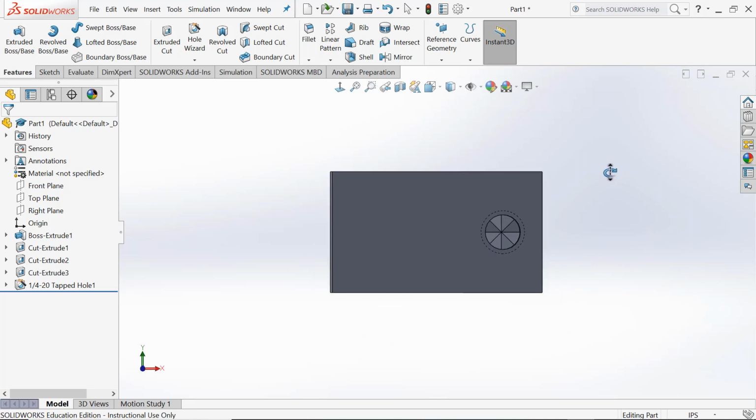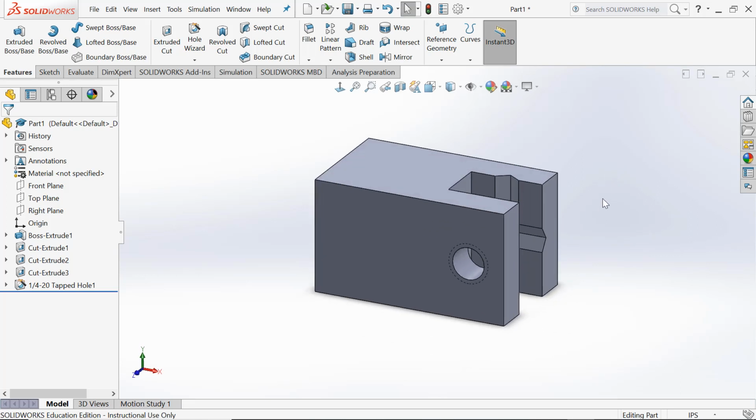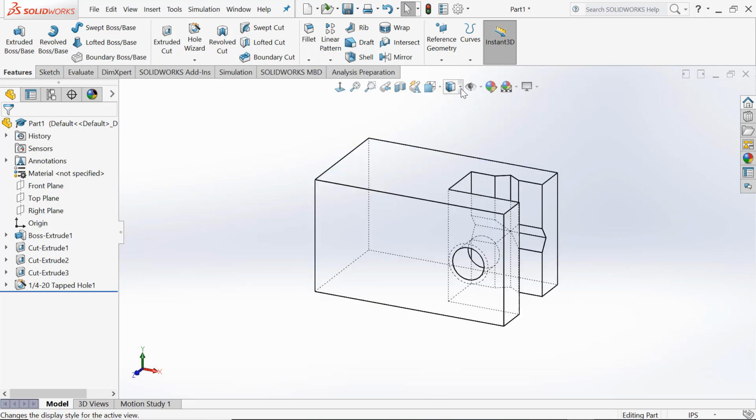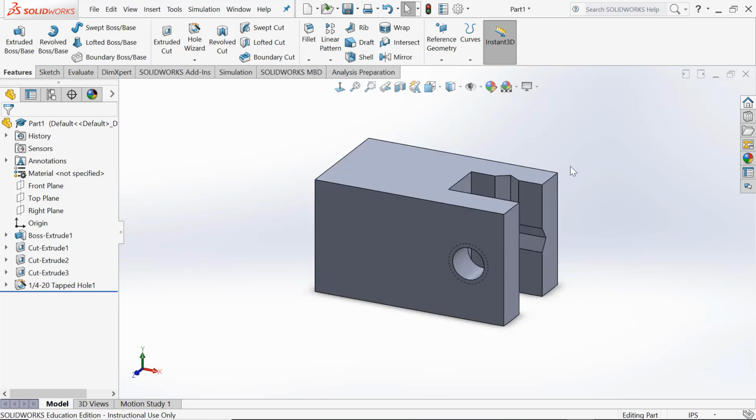So whatever numbers I was giving you in this little demonstration are irrelevant. It's mostly about the relations, how to use the transparency of a part to locate things that you can't see normally from that view, and how to use the select midpoint to help orient and align things.